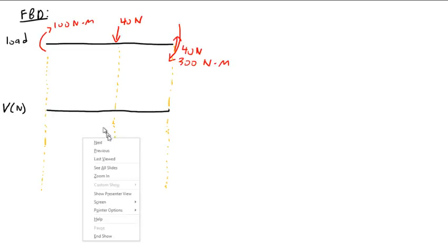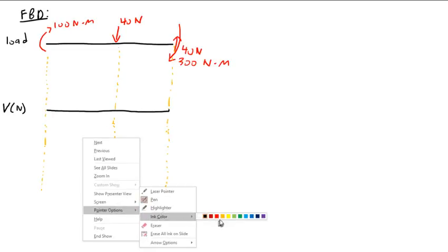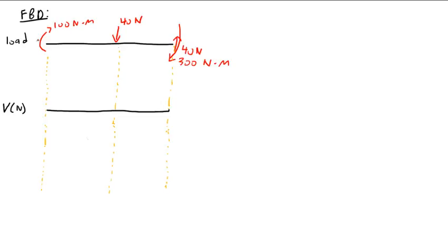Alright, so there is no shear here. This is a free end. I only have a couple on there, but there's no shear there. So from here to the center of the beam, the shear is actually 0. The moment will not be 0, yes.